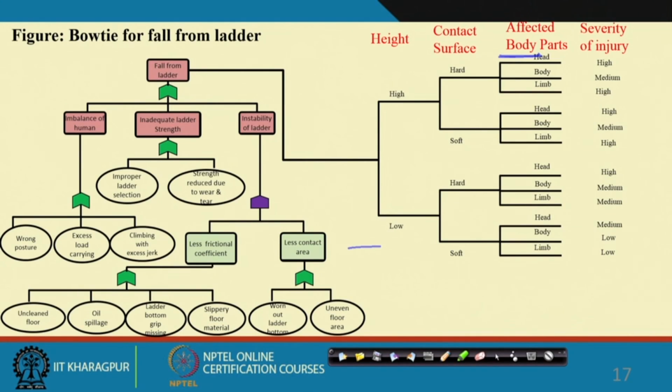Understanding accident scenarios means knowing the path from hazards to accident, and when you have a safety critical system, it is better to use the bow tie in the sense of fault tree and event tree together. Saying fault tree and event tree together is another simplification of the bow tie. It does not mean that a bow tie always requires a fault tree and event tree.